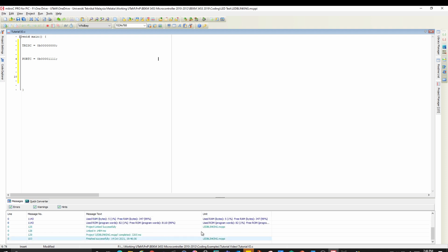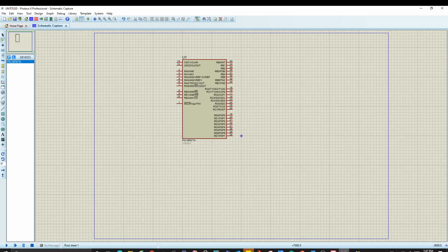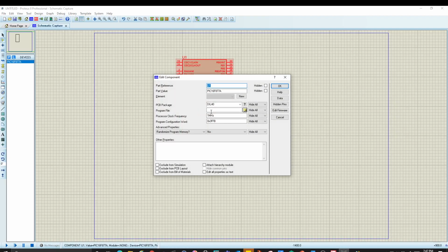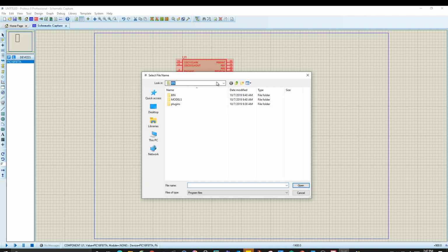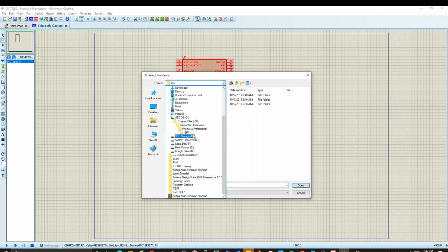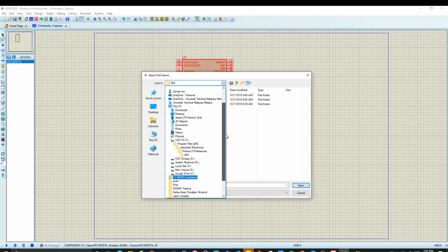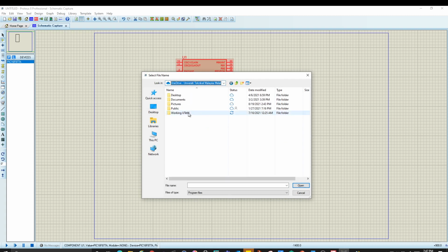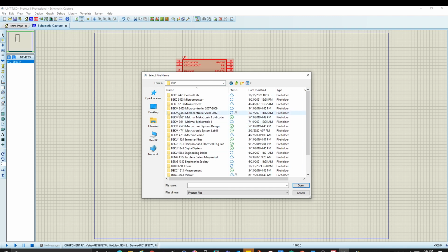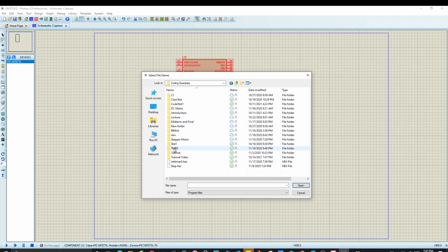There's no problem here, right? So you can go to your Proteus. Okay, done. There's no red colors over there. Then you can start to set up your simulator. This must be 20 megahertz. So where's the file? The file should be the tutorial just now under my OneDrive. SPMP, for example, tutorial studio, right? Is tutorial.